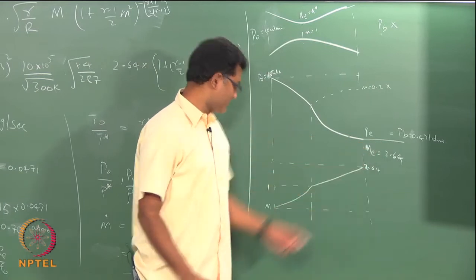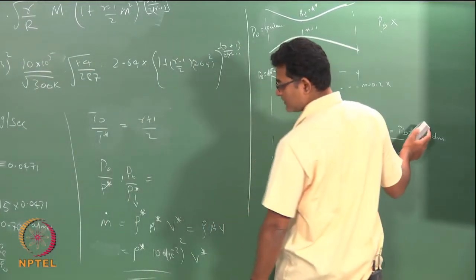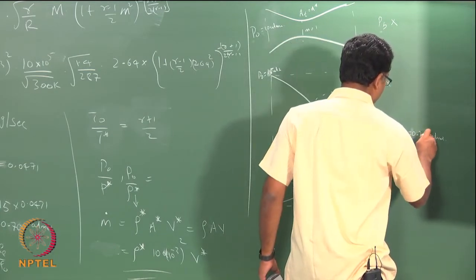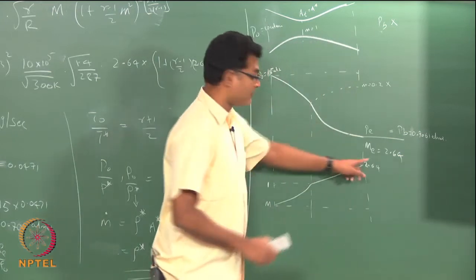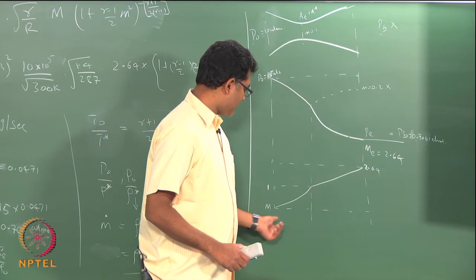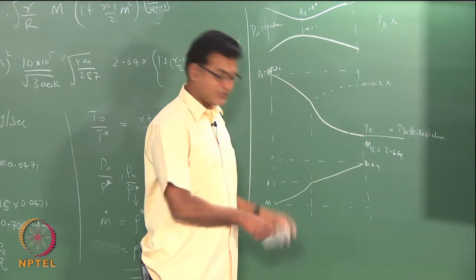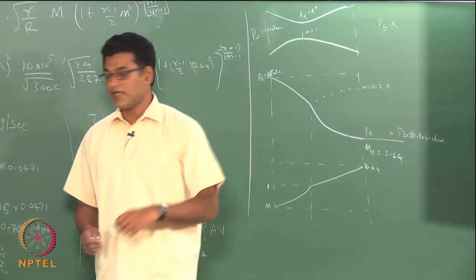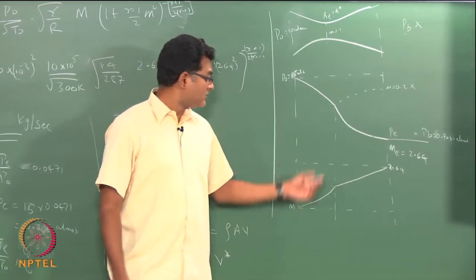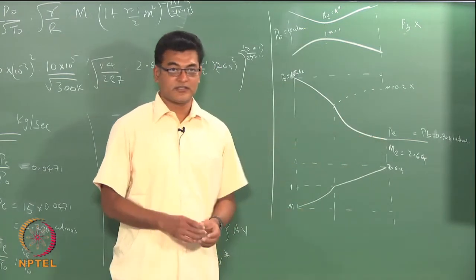The back pressure would be something else, which is 0.706. The exit Mach number has remained the same, there is no change there, and the Mach number plot is the same, except it is just stretched a bit. The throat Mach number is still M equals 1, the pressure ratio is adjusted in such a way that the exit condition is same.